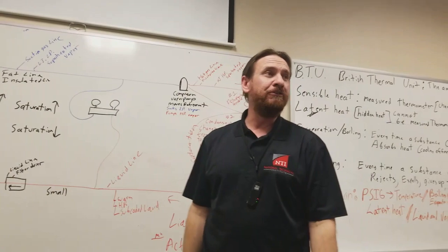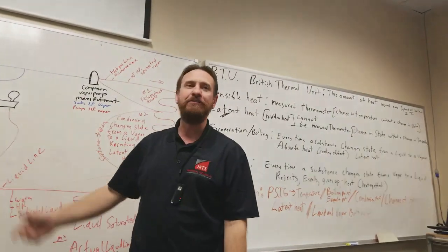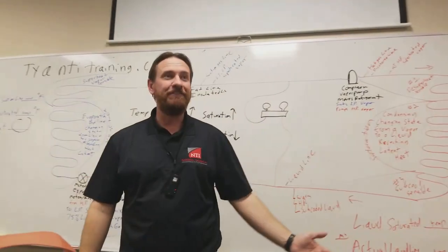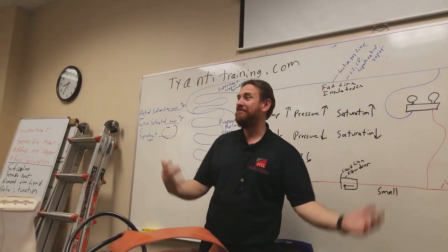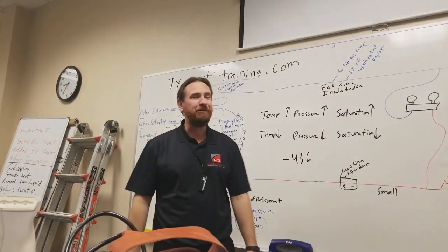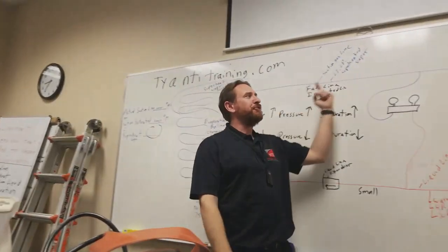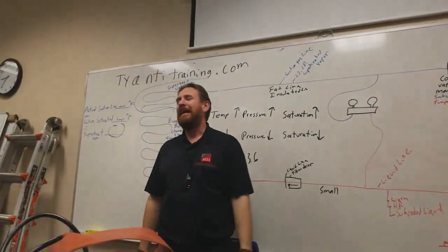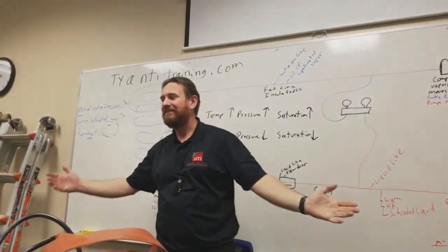But a lot of people don't do it because they want to save time. Walking to the truck, grabbing a nitrogen tank, and letting it free flow is a big problem for them. So, either way, I'm not going to say that I've never brazed without nitrogen, but I'm going to say I make a very valiant effort to braze with nitrogen almost every time. So, if I'm running nitrogen through the lines, can there be oxygen in the lines? If there's not oxygen, can there be an explosion? Will it be safe? Absolutely.